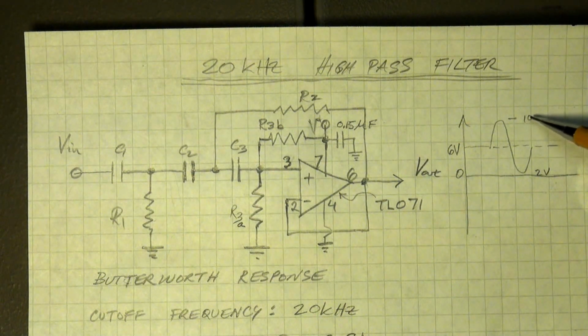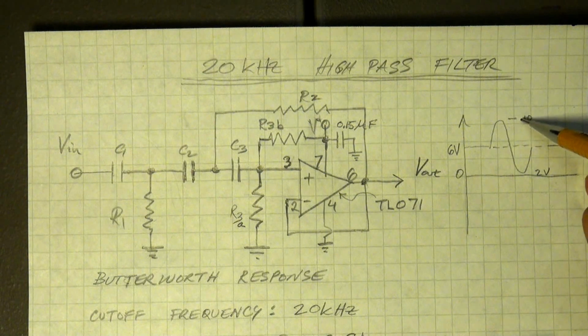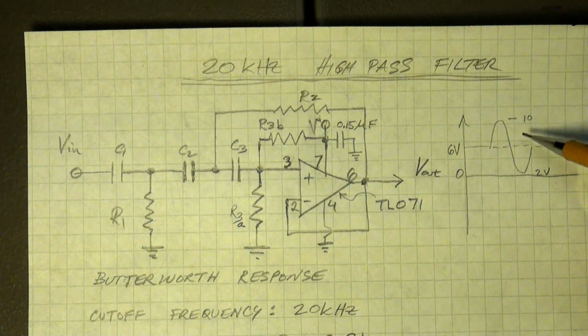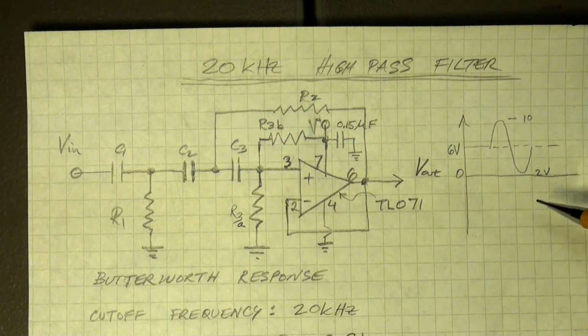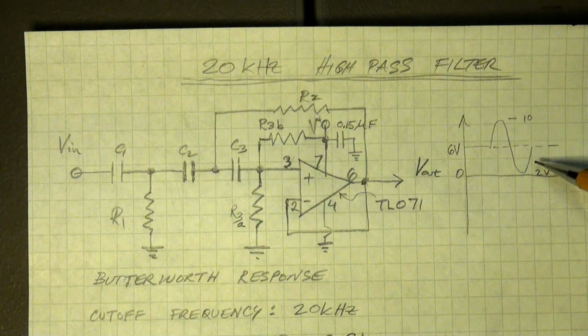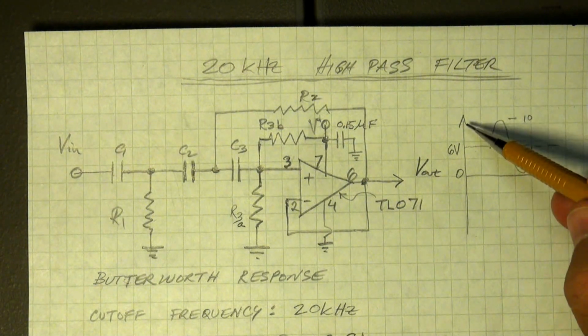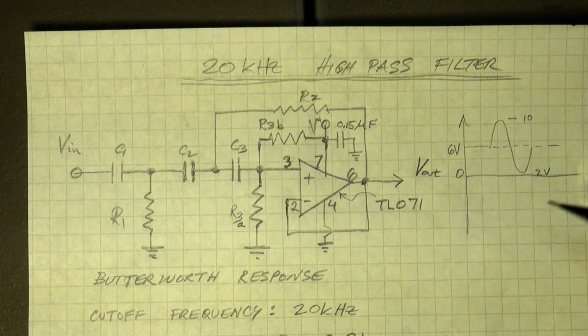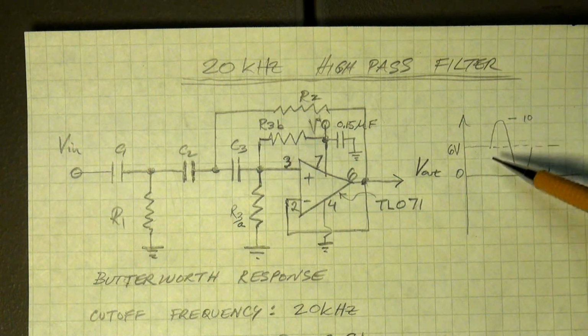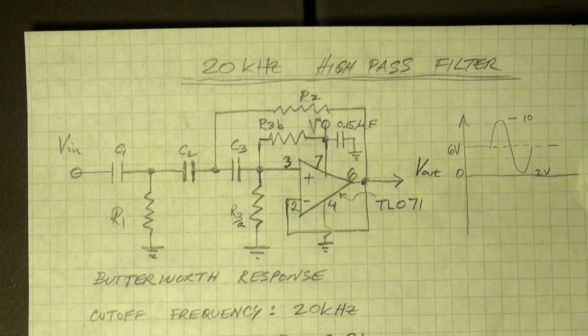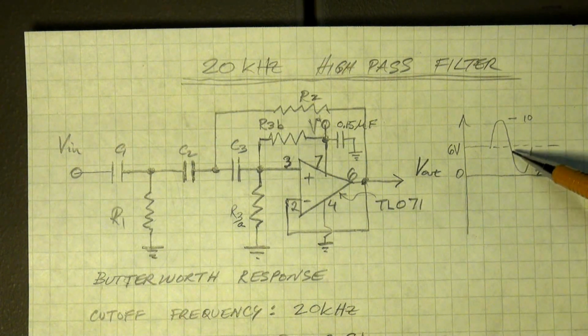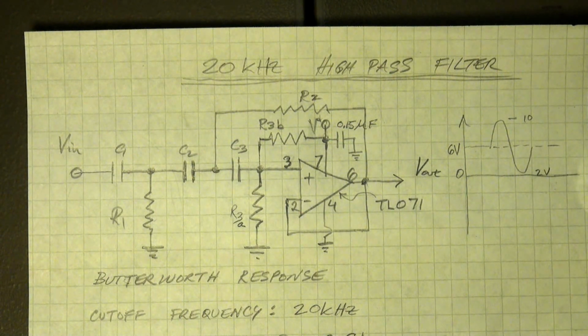You'll probably get a maximum of 10 volts of positive swing, and maybe down to 2 volts on the lower swing. So that will sort of maximize the dynamic range I have with a 12 volt power supply, about plus 5, maybe minus 5 voltage swing on input signals.